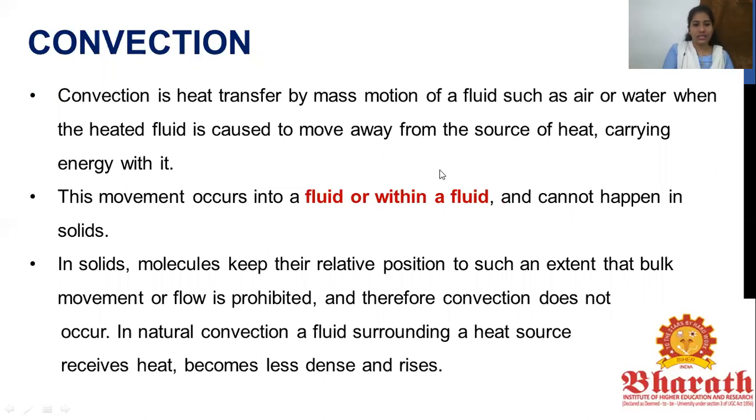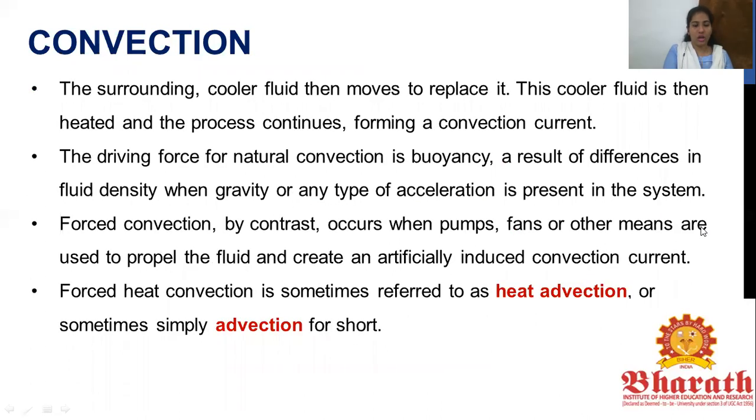So what exactly is happening is that the movement is dependent upon a fluid, right? In solids, the molecules keep their relative positions to such an extent that the bulk movement of the flow is prohibited, and thereby convection does not happen. In natural convection, the fluid surrounding the source receives the heat and thereby becomes less dense and rises. The surrounding cooler fluid then moves to replace it. This cooler fluid is then heated and the process continues.